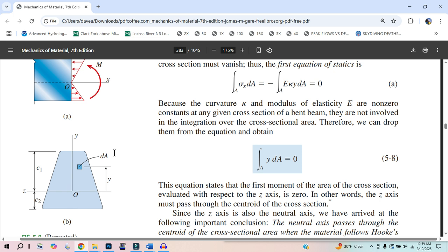Yeah, just the fact that you could have a heavy person on one side of a teeter-totter, a light person on the other, and there's a place where you can put the pivot point of the teeter-totter where both can be balanced. Because that's synonymous with this. The one mistake you can make is thinking this centroidal axis is just where the area up here is the same as the area down there, and that is horribly wrong. I make that mistake, not on purpose, and then try to make it on purpose too, to make sure I don't make that assumption. Just because you have leverage, you know what I mean.